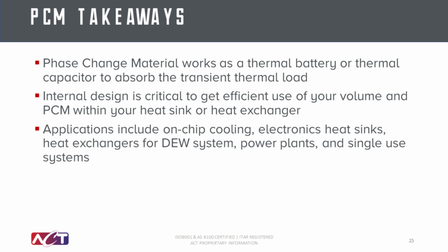So a quick summary for phase change material heat sinks is that they work as thermal batteries or thermal capacitors to absorb transient loads within systems. The internal design, specifically the fin structure, is critical to efficiently make use of your system and all the volume of PCM. And a lot of the applications are still developing. So we see a lot of, again, single-use devices, a lot of directed energy applications with high loads and long off cycles. But there's a myriad of other applications that we have customers reaching out to us to try to scope and design to.